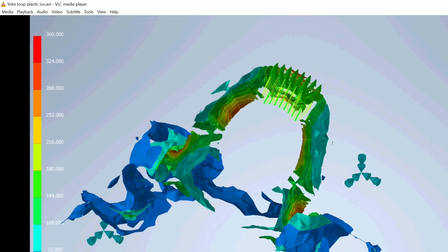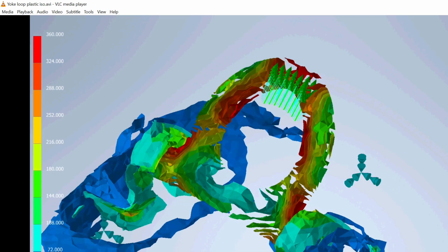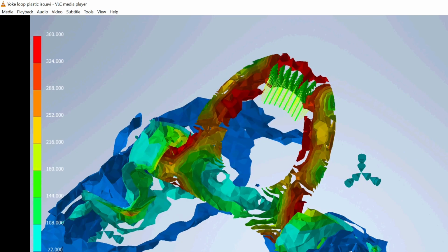But another way to see this is with these ISO curves, and you can see that in this large load, this area is basically holding on for its survival at stress levels that are relatively high. S355 steel, once multiplied by a coefficient, is 320-ish, and this area has some stresses within that range, while the top one is just pretty much completely on the edge, pull through.